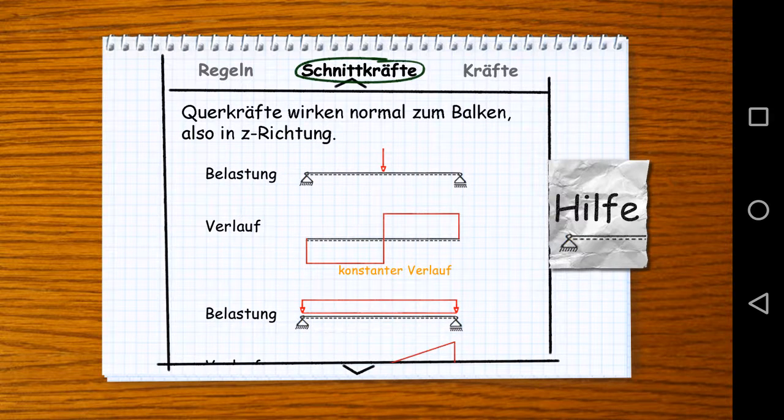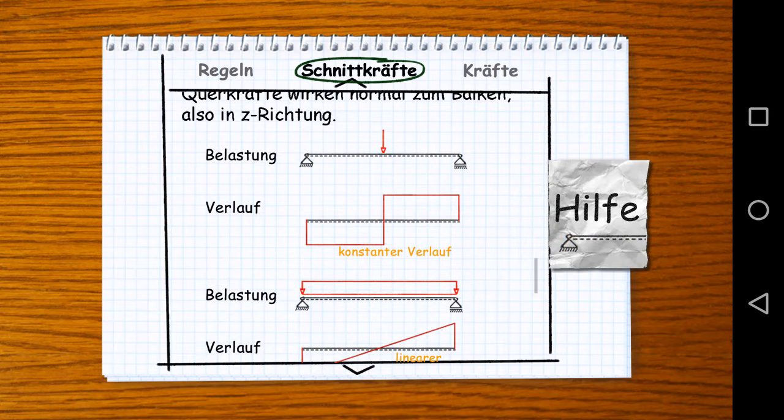But as a rule of thumb, what I will tell you here for the calculation of shear forces is basically to read your beam from the right to the left, so not from the left to the right. Just look at the beam from the right to the left, and every time you have any force perpendicular to the length of the beam, you just draw a jump in the direction of that force with the value of the force basically.